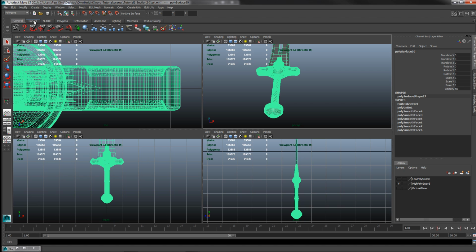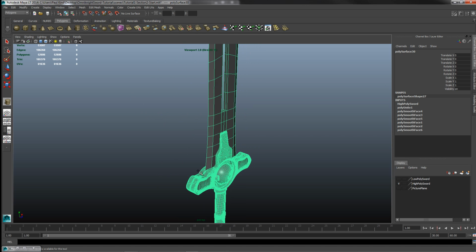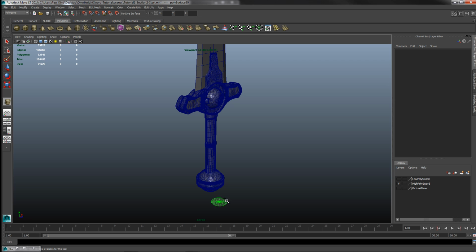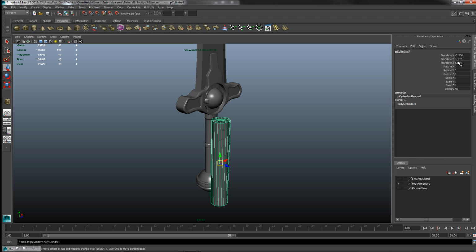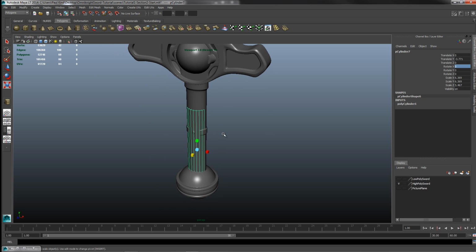But yeah, let's go into polygons. Let's grab ourselves a cylinder, go to our perspective view, and start drawing out the cylinder for the base. Let's put it at 0, 0, 0 and move it into position. We've done all this before. This is actually much easier than anything we've done, so this is going to be a cakewalk for you at this point. It's more the theory now than the difficulty of what we're doing. We've done the hard stuff, and this is just the process now.